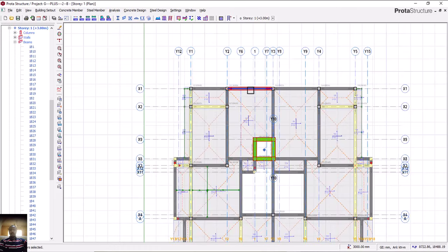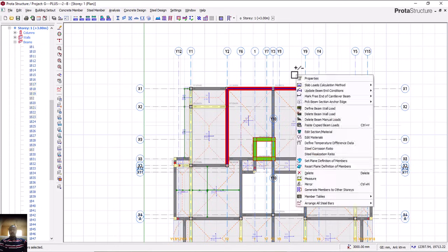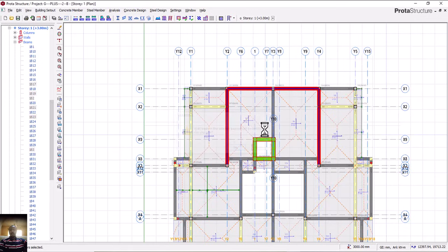Okay, so we are not supposed to have a wall all through this place. Is that okay? The wall is around here like this and this place. I'll delete this one. Click on this, this, and this. Then right click and click on delete beam wall load. Click on it and say yes. Since I've said yes now, my line load is on this line. Is that okay?